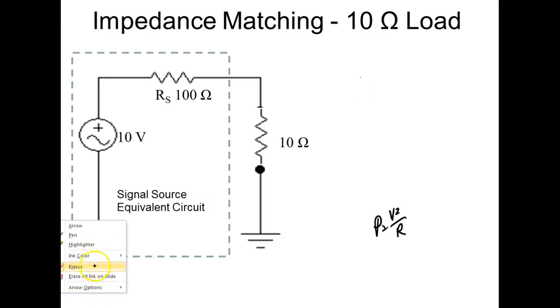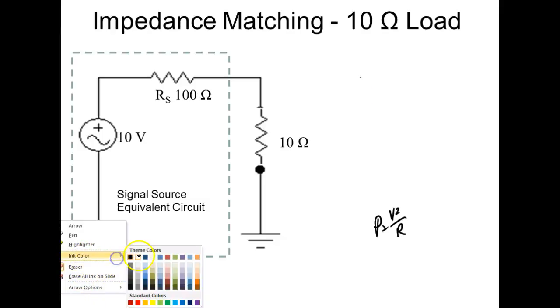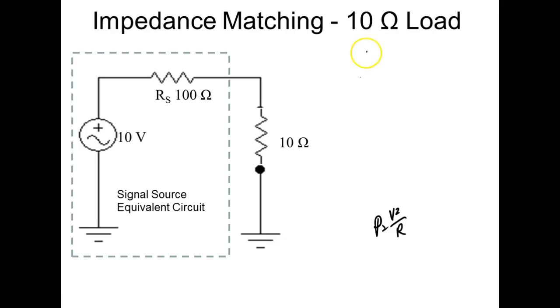So the power across R1 would be equal to 10 ohms divided by 110 ohms, right? Times, what are we applying to it? 10. And then as soon as I hit equals, I'm going to square, and then divide it by 10. And this is going to give me my power. So we're combining the voltage divider formula with the power formula, and that way we can do it all with one equation, right? Anybody got it?